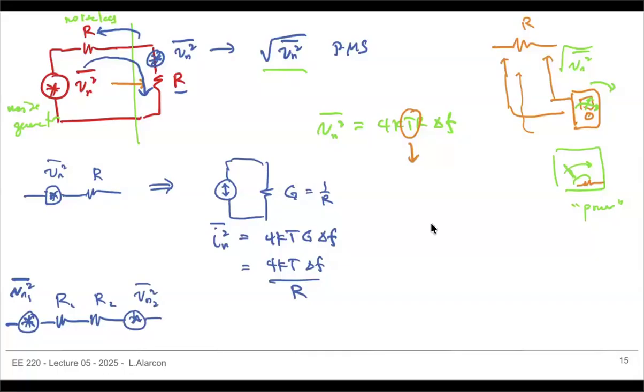When you add, you either add instantaneous voltages, but we can't get instantaneous voltages, so what we add are powers. We cannot add RMS because we don't have any phase information for RMS.